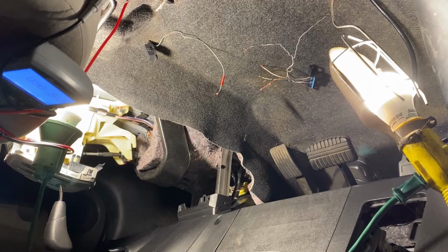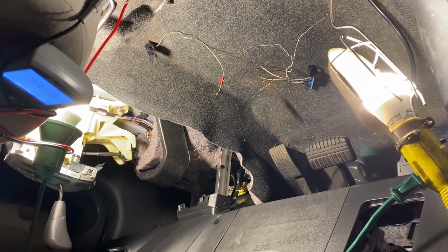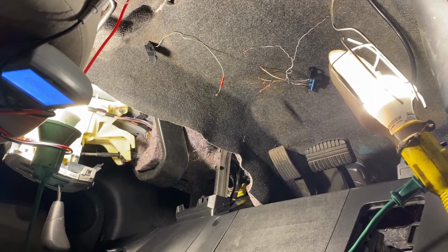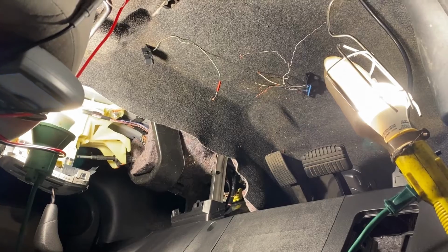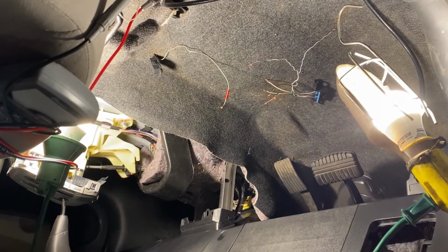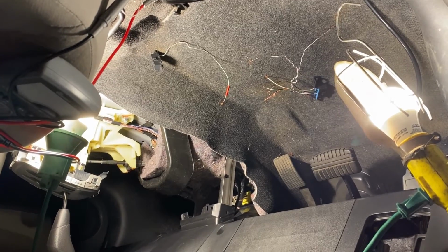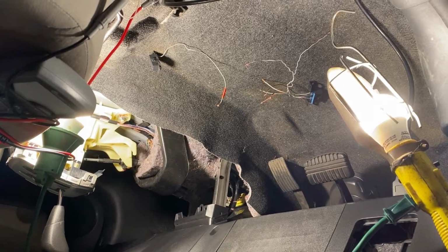The only test that I need to try is to dump the original file with the crash in, and see if I get this with a crash. If I can read it after I dump the bad file with the crash on it, and I read the error, that means the clean file that I wrote in the EEPROM is bad.